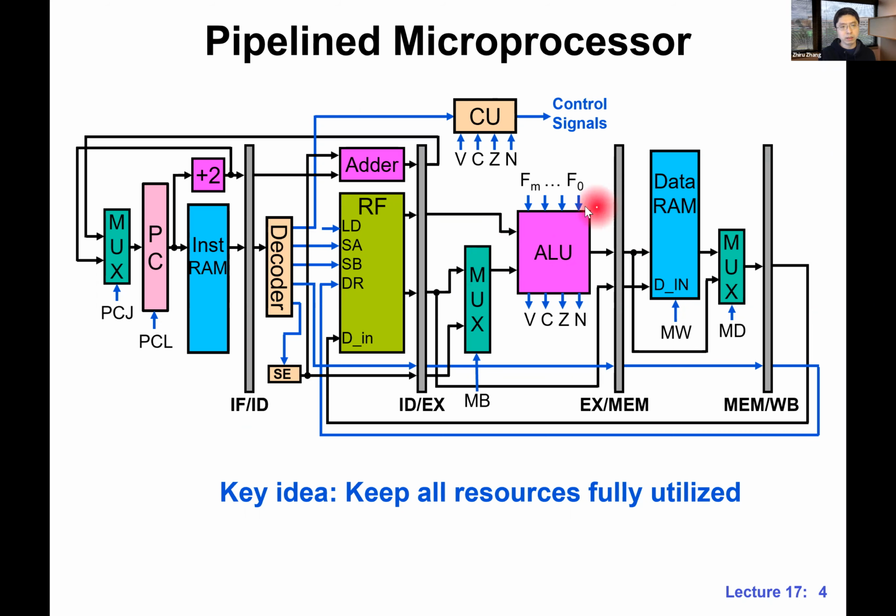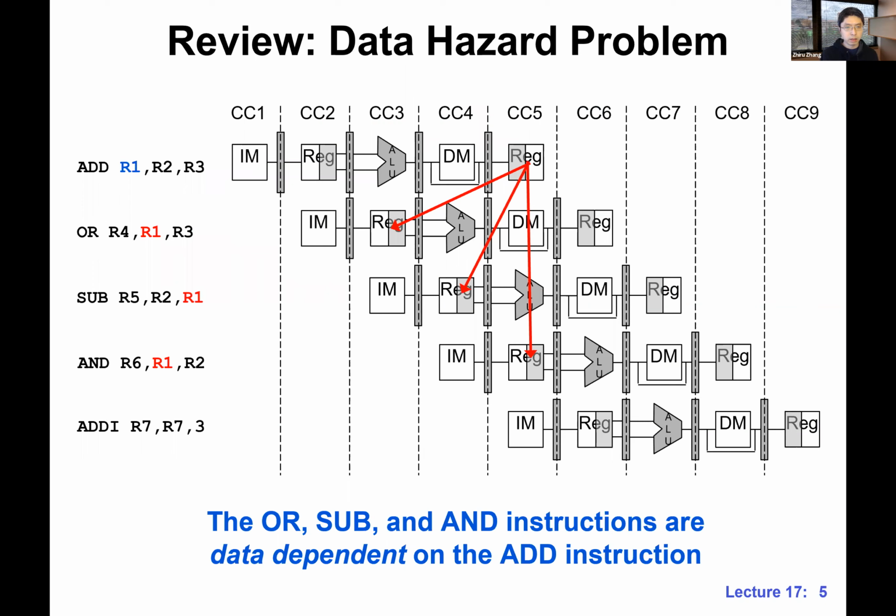logic. Some of them are already showing up here. So we actually need to add additional wires at least, and those also contribute to delays. And today we're going to see we need to add additional muxes as well. There's always a trade-off, but in general, if the pipeline is busy most of the time, we get performance improvement. Any more questions about the intuition behind pipelining? Okay. If not, let's talk about some of these non-ideal cases.